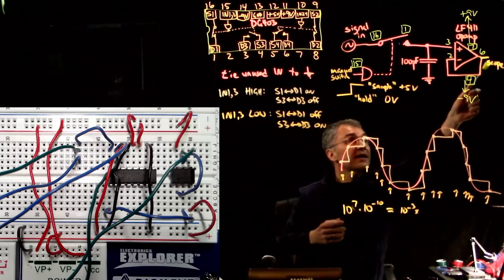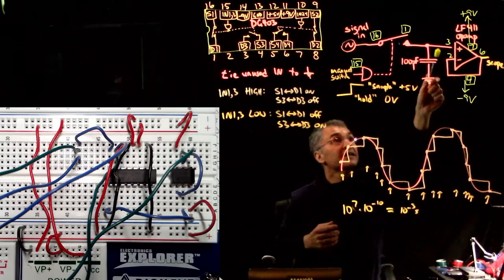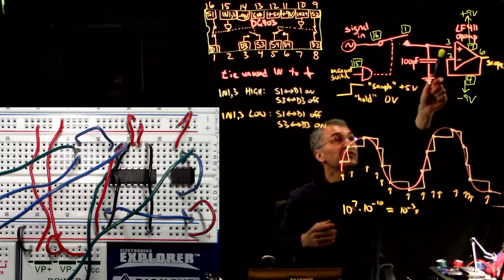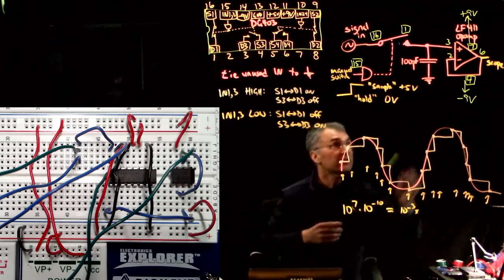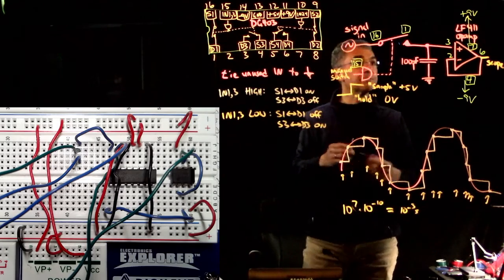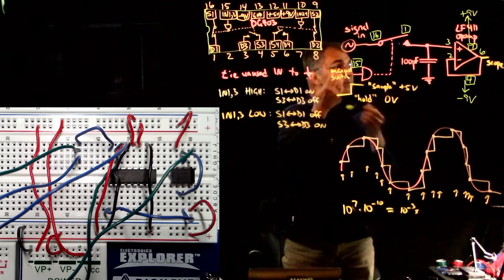So you say, okay, I'll connect the scope probe over here, and this is a very, very high impedance voltage probe, the input to this FET input OpAmp. So this gives me a way to observe the signal without disturbing it. So we have to remember how to wire up an OpAmp.